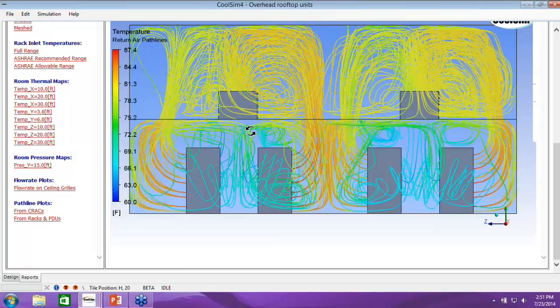That's occurring, Magnus, you can see, and that's of course because the RTI is not 100%. We don't have enough supply air, so those racks have to breathe their own exhaust because they don't have a choice. The only other choice is that the fan in the server goes into a fan curve mode where it can't push enough air, which wouldn't happen in this case because there's no impedance, there's no resistance, and it's just going to breathe its own exhaust.